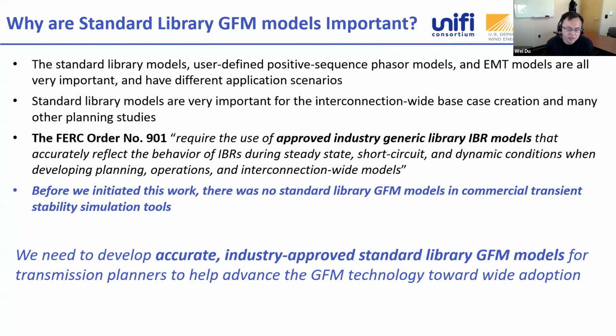And also a very important thing is that we know the importance of standard library IBR models, but before the UNIFI consortium initiated this work, there were no standard library grid-forming inverter models in today's commercial transient stability simulation tools. We know that maybe in the US, PSSE, PowerWorld, PSLF, and TSAT are the most widely used transmission planning tools. But there were no grid-forming inverter models in those tools.